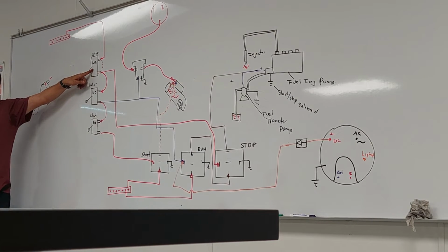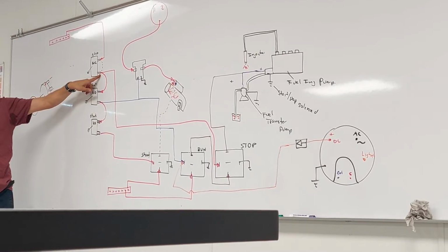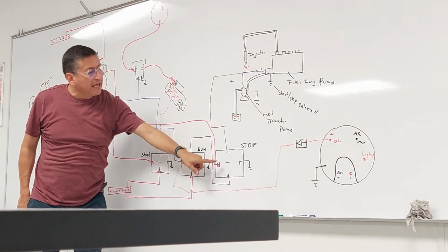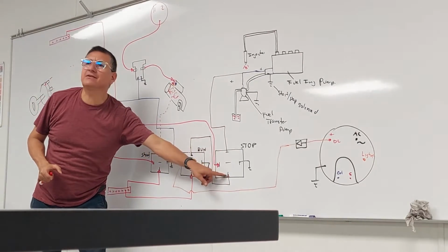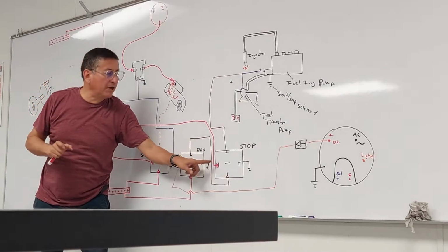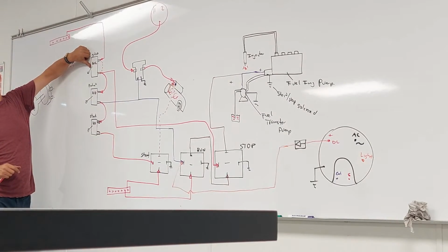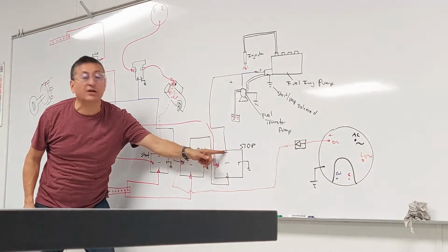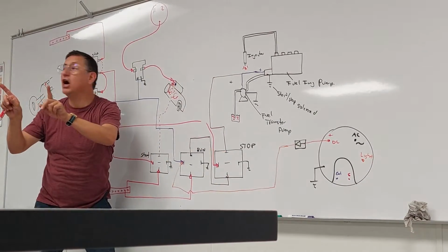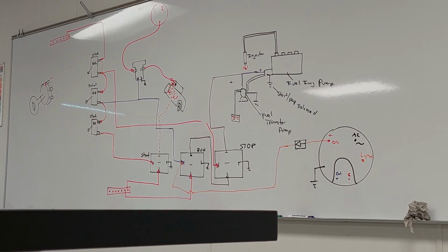What happened with that switch? It's normally closed. What is the meaning of that? You have constant power here, no? Because you have constant power here, that relay is constantly activated. This and this are connected all the time because it's powered all the time. What happened when I press that button? I interrupt that current. And what happened with this connection? It is open, and I don't have fuel. And finito. Stop. Good?